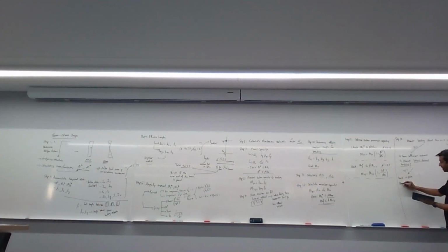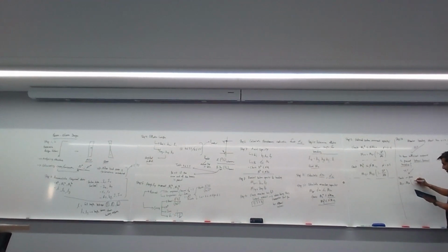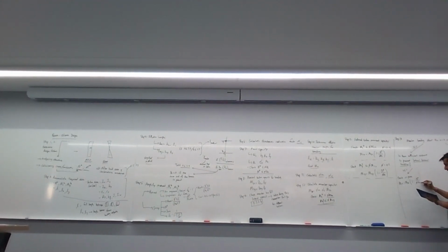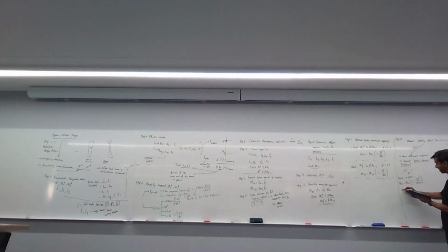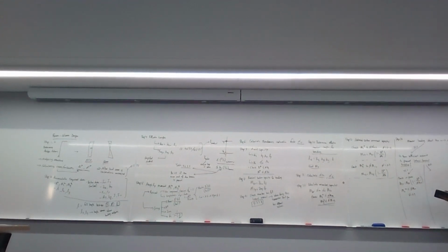requirements. MIX equals MSX times 1 minus N star over phi NCX. And then you check MX star less than or equal to phi MIX. Phi is equal to 0.9. If the answer is no, I'll just write it out here.